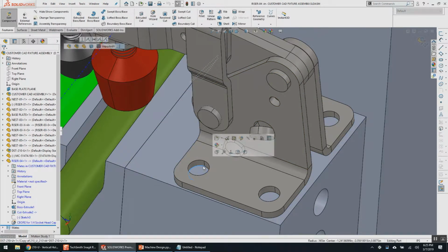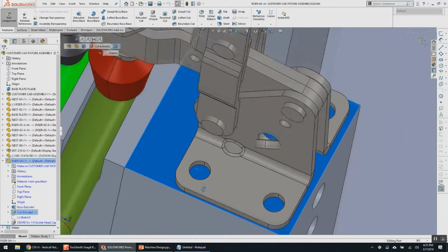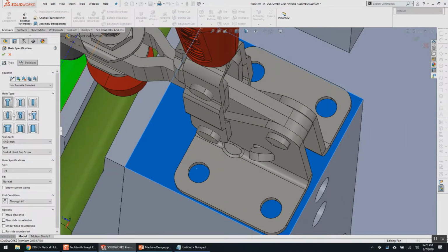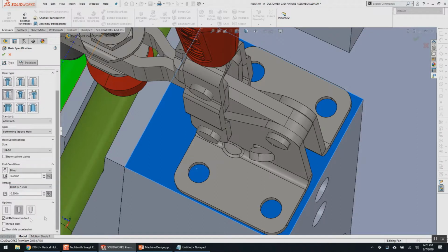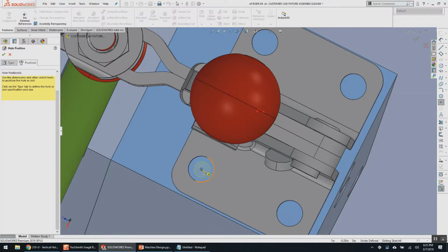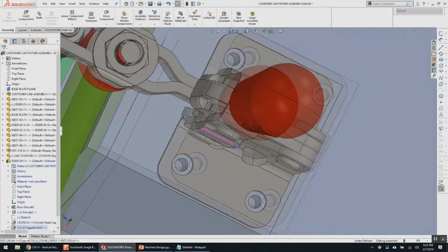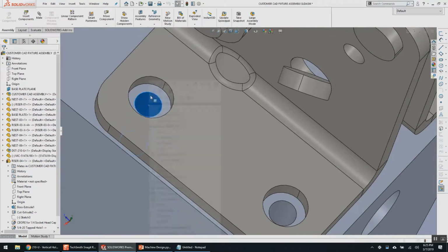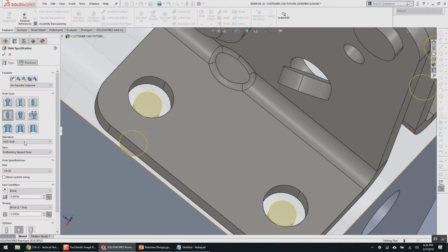Then here I could edit this part. What arc is this? So 1/4 inch will work. Insert a hole wizard here, tapped holes, 1/4. Don't want to go through all on a tapped hole. Somebody from the machine shop, if they're doing their job well, will give you a friendly and polite call, in my opinion. And maybe those holes are a little small. We can maybe move to 5/16.